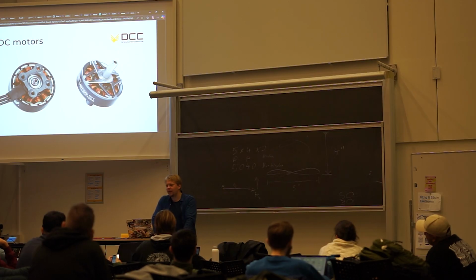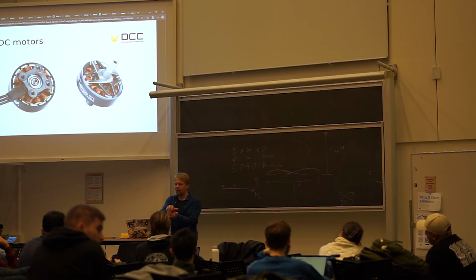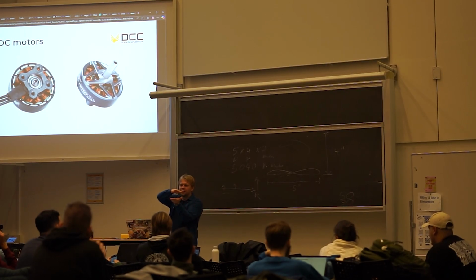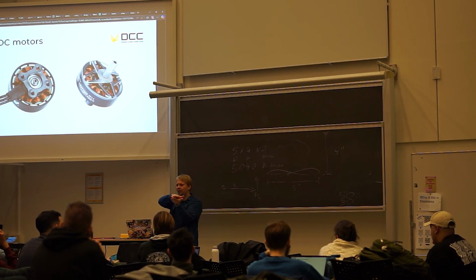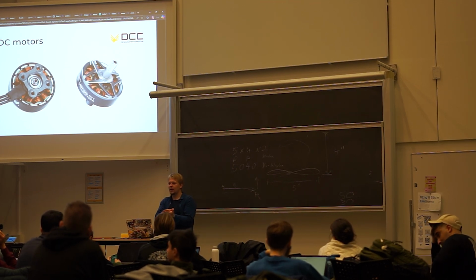You don't have to make it, but for as high efficiency and power density as you can get, you want it to be able to flow magnetic flux as well as possible. And for that, you need to stack super thin metal plates, with a little bit of dielectric in between. Super compact. That's to reduce eddy currents.